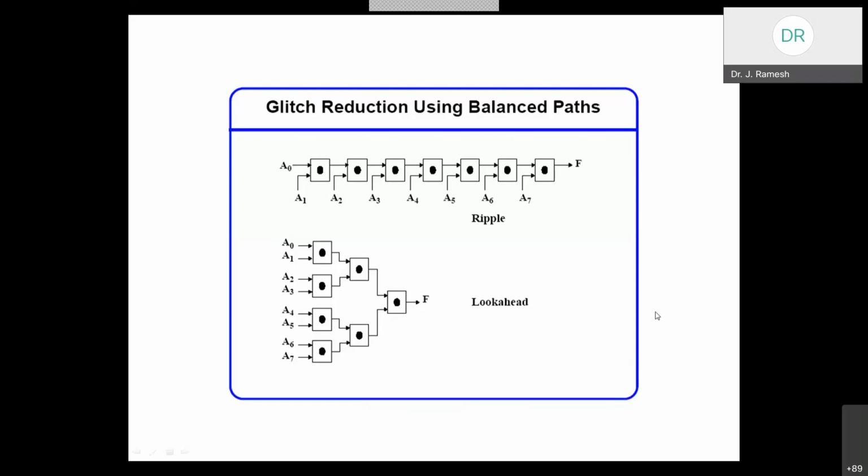We also proceeded to the switching activity of logic gates and calculated it. We compared and saw that NAND, NOR, AND and OR gates have less switching activity when compared to the XOR and NOT gates. So, for the purpose of low power design, the gates having minimum switching activity can be preferred. That is the point we concluded in the last session.